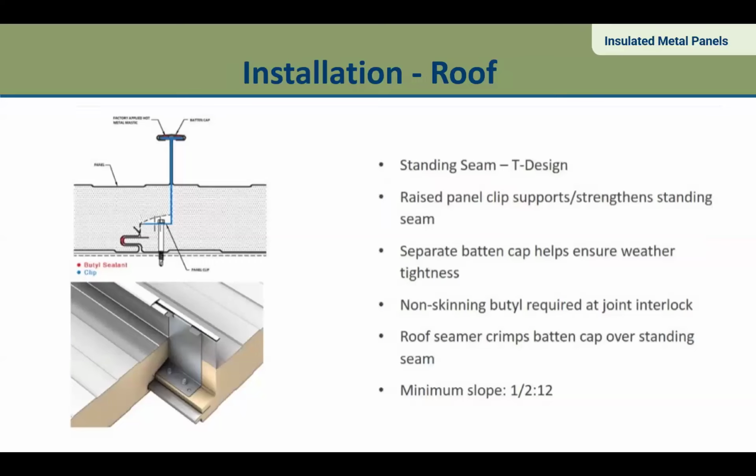There are insulated metal roofing products out there in this world too. These are great. They do come with the same design limitations, minimal ribbing and fluting, and 3.5 foot wide modules typically. There's a couple different seam locks. The one you see here is a T batten style. So you've got just the one tongue and groove connection at the bottom, and then you have your clip coming up, which actually integrates in with the seam and the batten clip at the top.